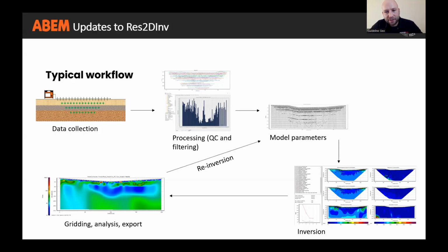And all of these data streams, along with detailed information on the measurements themselves, such as the measured voltage, variability of the recorded signal over the measurement cycle, the battery status during measurement, amongst other information, can be invaluable for data QC and also provide informed filtering choices and flexibility on filtering parameters.